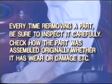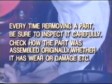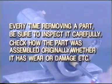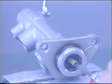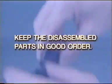Every time removing a part, be sure to inspect it carefully. Check how the part was assembled originally, whether it has wear or damage. This is important because some of the causes may be here. Keep the disassembled parts in good order.